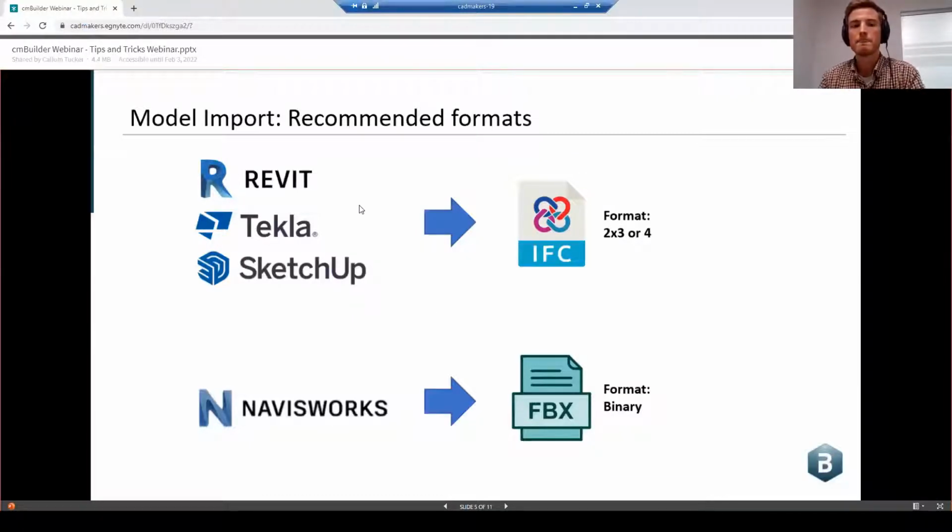Perfect. So a couple different softwares. It depends what you're coming from, what your architect is using, what the structural engineer is using, wherever you're getting the models from. Some of the common ones are Revit, Tekla, and Sketchup. For all three of those softwares, we would recommend going to an IFC file format for the import, which cmBuilder can handle. From Navisworks, FBX is the preferred file format.